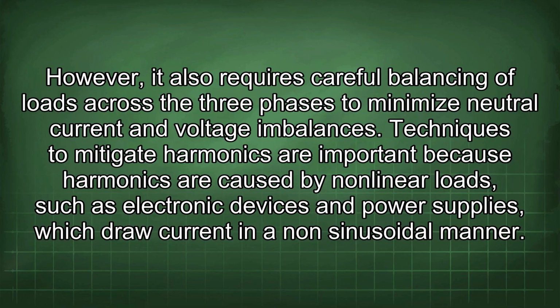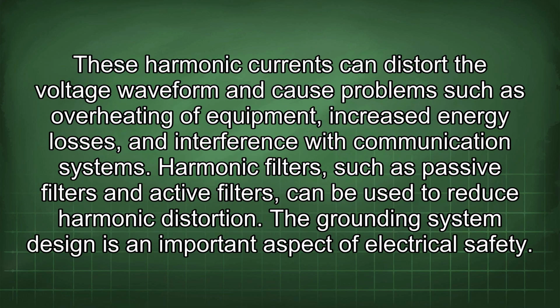Techniques to mitigate harmonics are important because harmonics are caused by nonlinear loads, such as electronic devices and power supplies, which draw current in a non-sinusoidal manner. These harmonic currents can distort the voltage waveform and cause problems such as overheating of equipment, increased energy losses, and interference with communication systems. Harmonic filters, such as passive filters and active filters, can be used to reduce harmonic distortion.